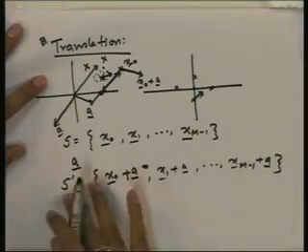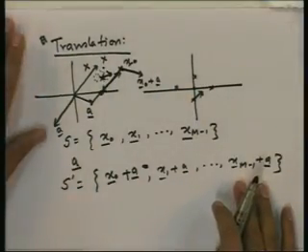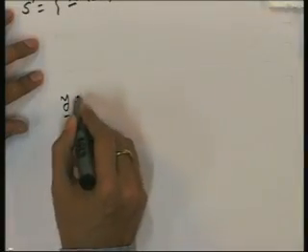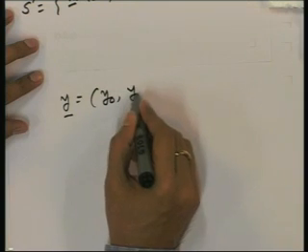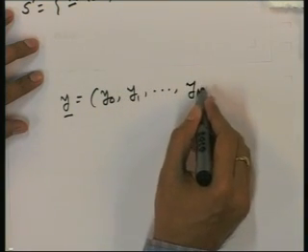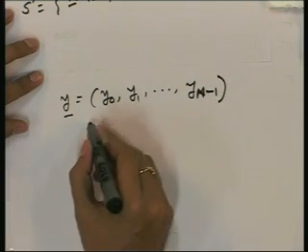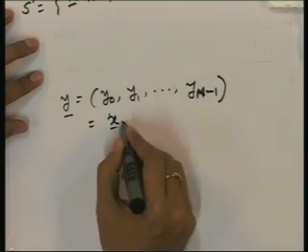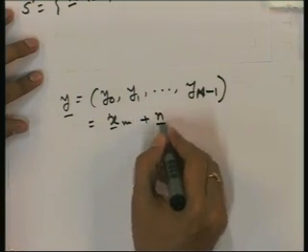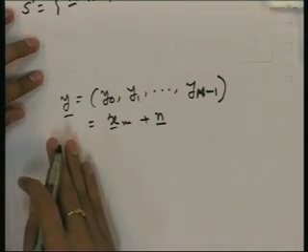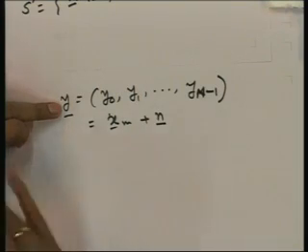How do we see that? Suppose the transmitter is using this signal set, and the receiver has received y of t, and it has also extracted the vector y using a matched filter or correlation receiver. This is the same as xm that was transmitted plus the vector n. So, this is what it has received after matched filtering.